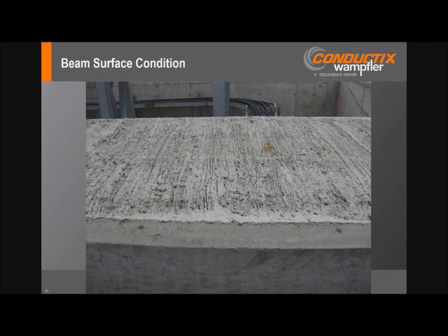So it's important that the guide beam surface is sufficiently smooth. Obviously it needs to have some roughness to ensure tire adhesion for acceleration and deceleration. However, when beam roughness is excessive and produces a rough ride, collector shoe contact with the power rail can be compromised. And this produces arcs and sparking and can lead to premature failure of the power rail contact surface.